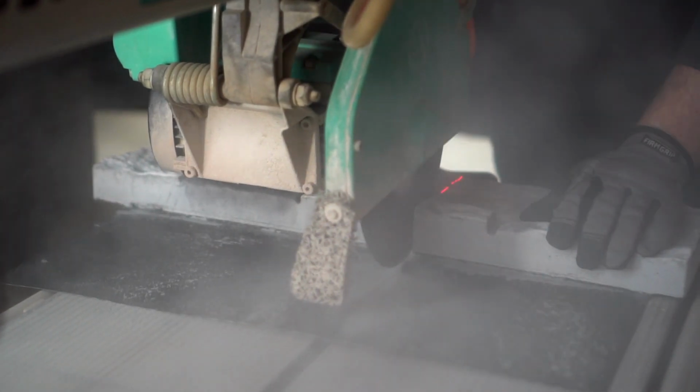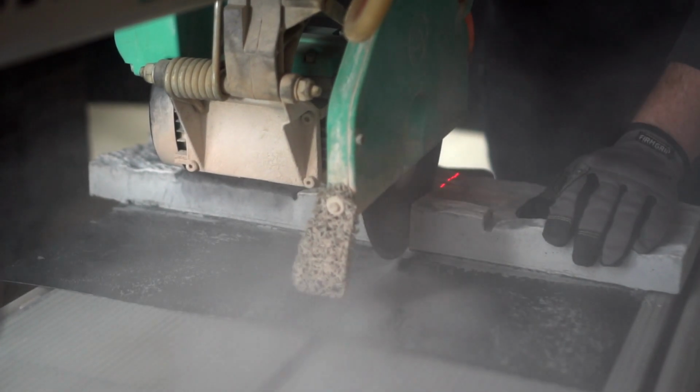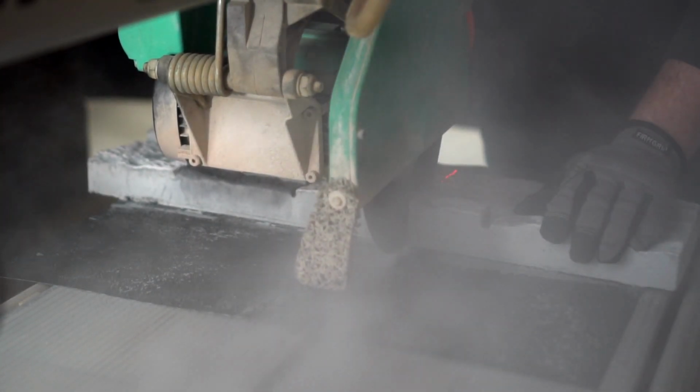Cut between 4 and 7 inches off the first flat panel on alternating courses to establish good seam offsets. Cut the stone per the cutting instructions.